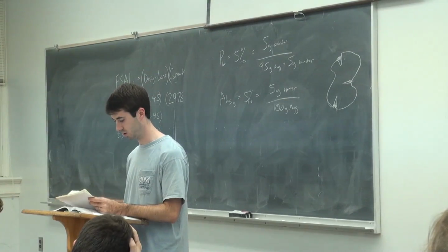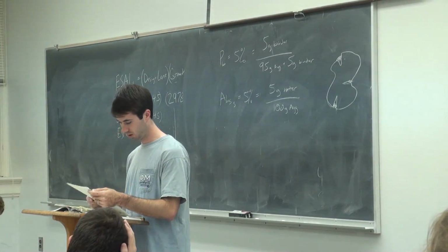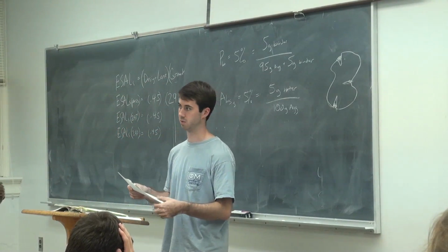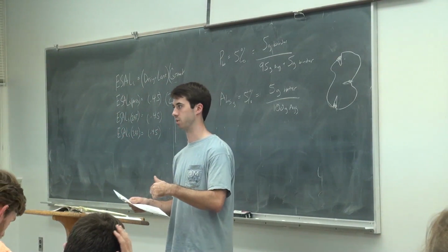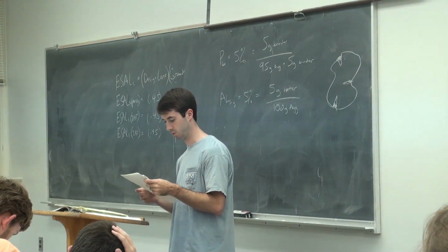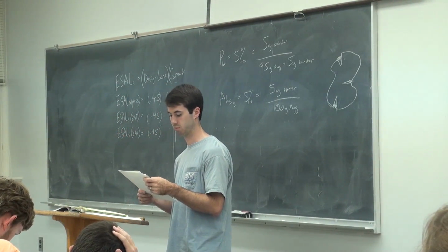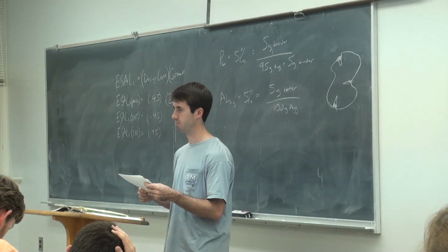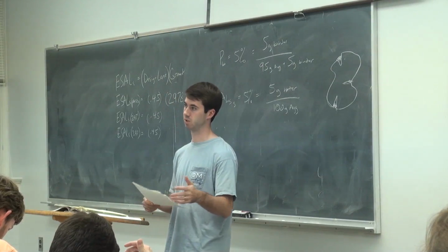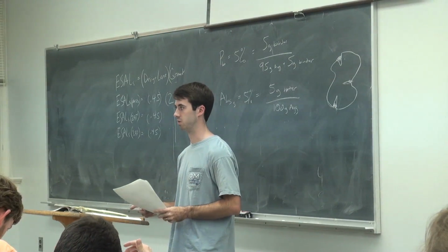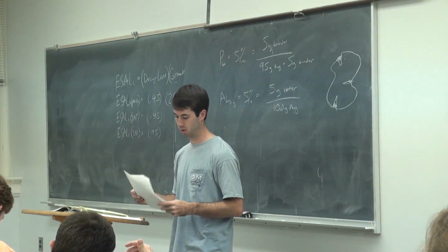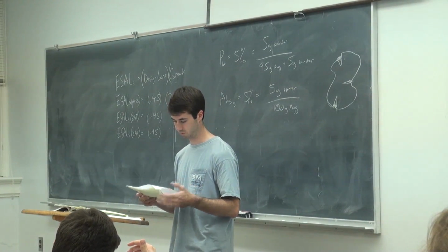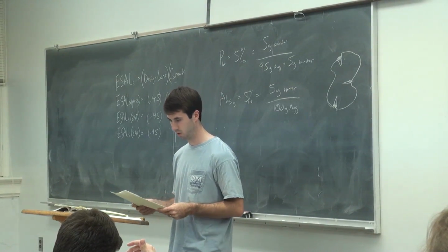One other thing to note about the PG grading system, just notice the criteria stays constant regardless of what temperature you're at. The temperature fluctuates, but the standard is the same. So that dynamic shear, 1 kPa minimum, it stays the same, and you just adjust the temperature that you graded at depending on whether or not it meets that criteria. And it's really the only place you can come in.